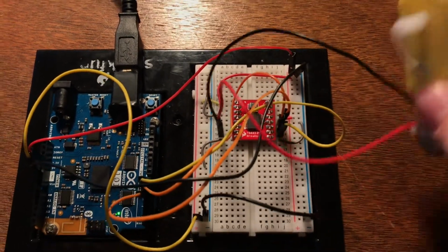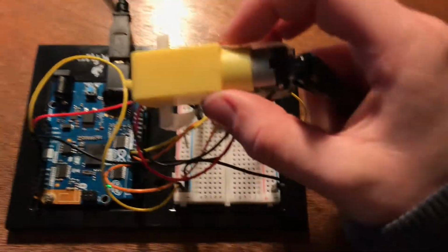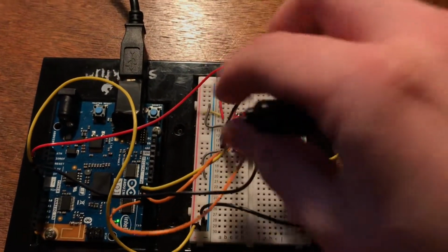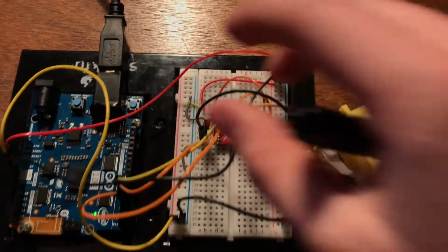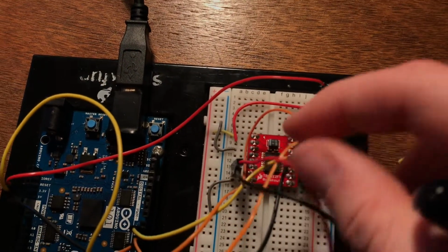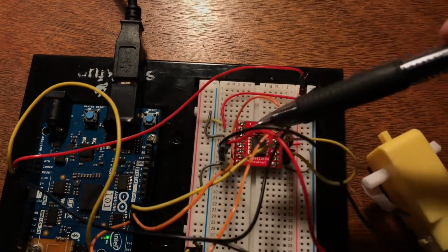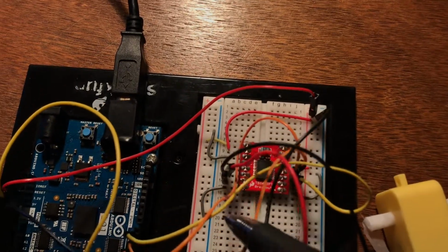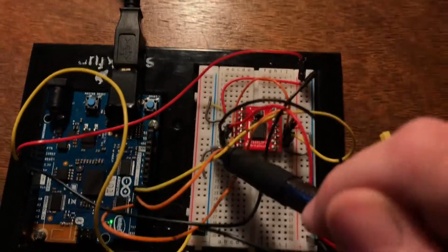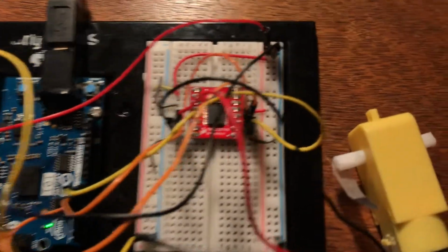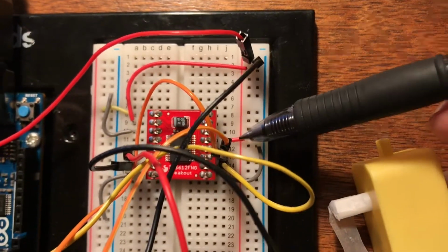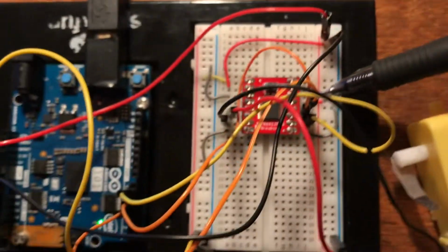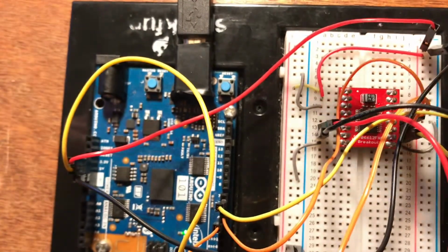And then we're going to be connecting the motor itself into these two pins here. So the ground wire of the motor is connected to this pin here, and then the red wire is connected to the pin here, and then it is all grounded again by this gray wire here. On the other side, we have the board connecting to the 3.3 volts through this red wire here. Again, 3.3 volts is over here.